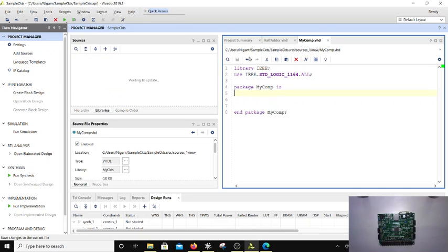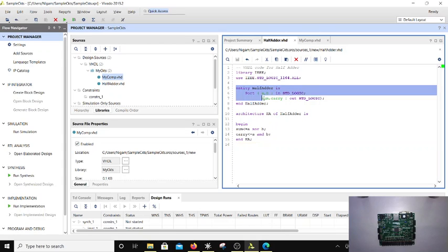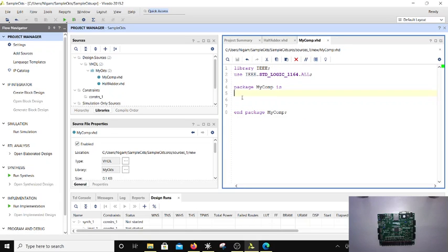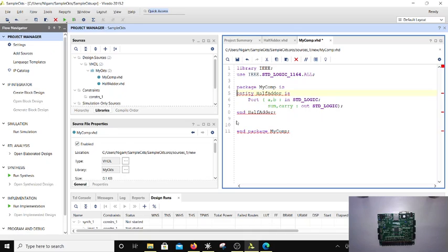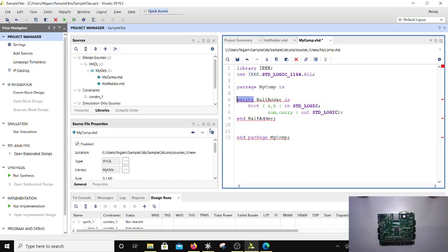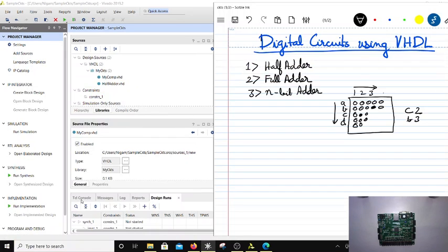So now what do I do with this package? I have to add a half adder component into this package. So I'm going to copy this as is, Control C, and paste it over here with Control V. Now entity is not going to be defined over here, so I will call this component, right? And then is optional, and then say end component. Here I can add a small text for myself on what this is. So this is a half adder, right? Just one second.